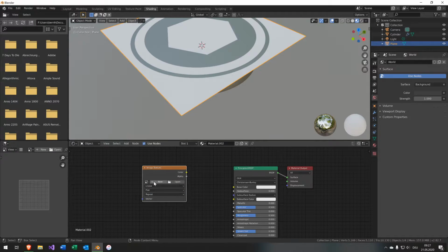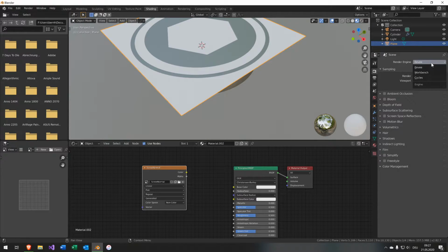And first we're gonna create a new texture and call this screw normal, which is the normal map for the screw. And we could set it to a 4K resolution, or maybe 2K would be sufficient for this tutorial. We don't need the alpha channel, and we will also use 32-bit float. Another important thing, change it to non-color because we're baking a normal map.